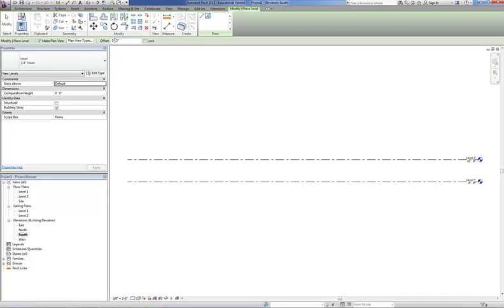So if I go to Pick Lines, now you can have any offset that you'd like. I'm going to show the offset as 10 feet because I want to show what happens or what could potentially happen if you already have a level that's at 10 feet. So I'm going to set the offset at 10 feet. And I want Make Plan View checked because I'm going to create 2 additional levels, but I want floor plan views to be associated with both of those.